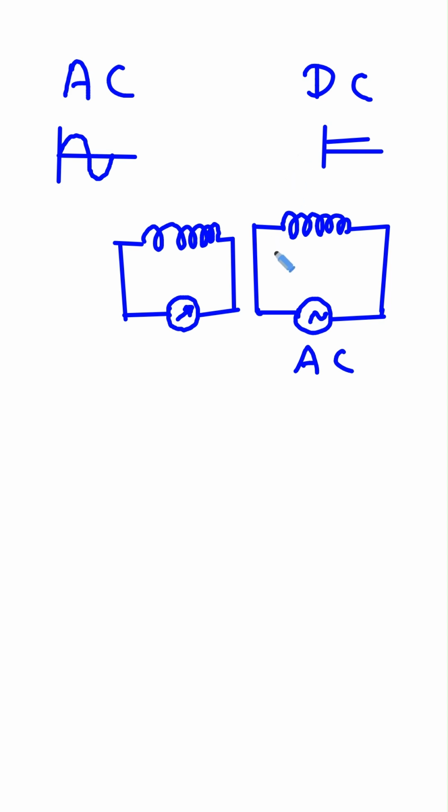And here is something important: if you connect pure DC to a transformer, it might actually burn. It is very dangerous. You should not connect DC to a transformer, because DC flows continuously through the coil. It can cause overheating, damage insulation, and destroy the transformer over time.